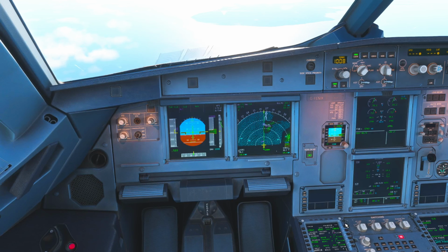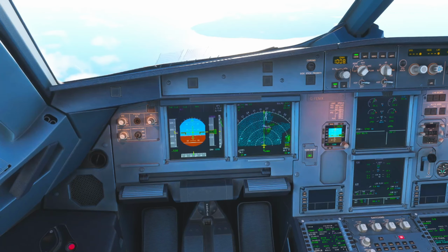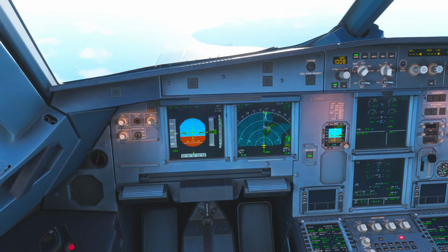Today I'll be explaining about autopilot in the Airbus 320. The autopilot sends digital signals to the flight control, which in turn moves the flight control surfaces. The autopilot doesn't move the passive side stick in the Airbus 320, so there's no direct feedback for the pilots on their control input devices. The pilot has the option to deflect the controls to immediately disengage the autopilot, but it usually requires some breakaway force and disengagement isn't soft.